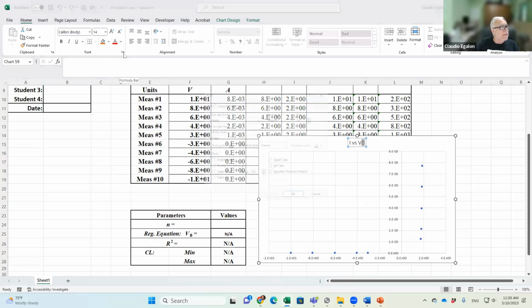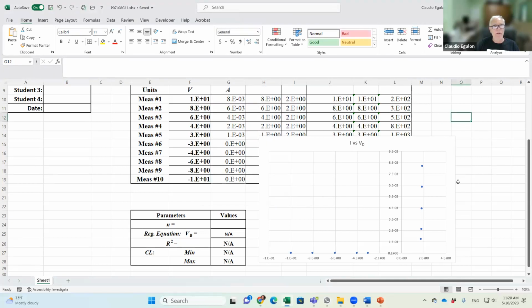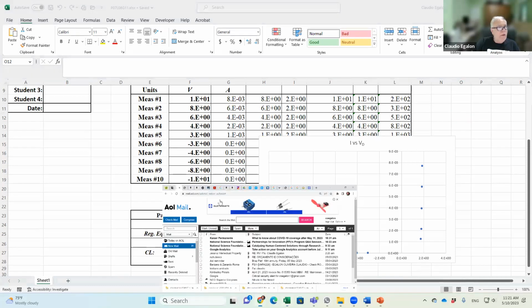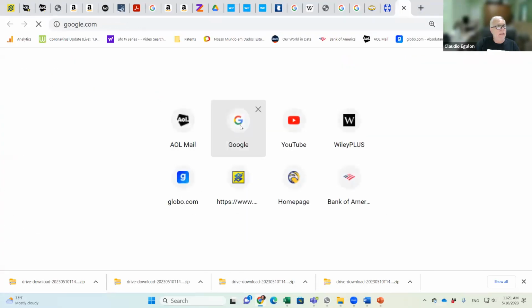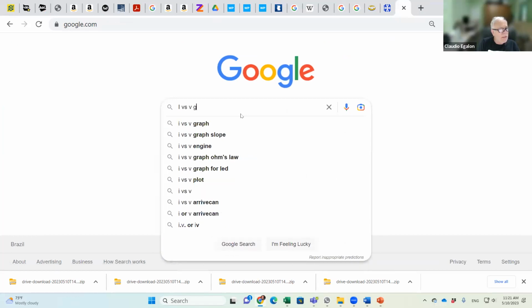And VD, the voltage of the diode, instead of VD versus I. Note that the current remains very low, remains at 0. And then suddenly at a given voltage value, the current just takes off, okay? At a given voltage value, the current just takes off very high. And you can look at that in the I versus V graph.